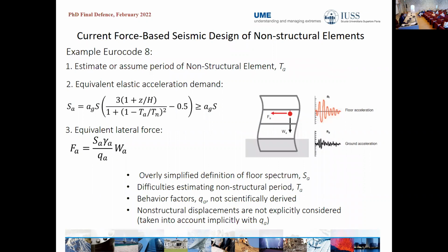So because of this, current seismic design guidelines usually provide a force-based seismic design procedure to ensure that the non-structural elements will achieve a certain performance during an earthquake. All of these procedures follow similar basic principles. I will use Eurocode 8 as an example here. So usually a force-based design procedure for non-structural elements follows three steps.